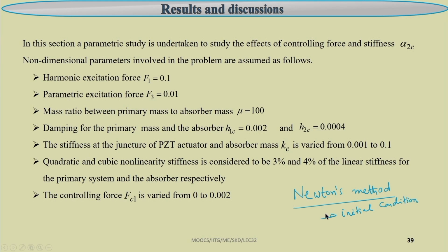So, to find this initial condition, you may solve this equation by using ODE45 or by using the Runge-Kutta method, and then taking those responses as the initial condition, one can make further study to find the response of the system. Otherwise, one can use this continuation technique to find the response of the system for a wide range of frequency.